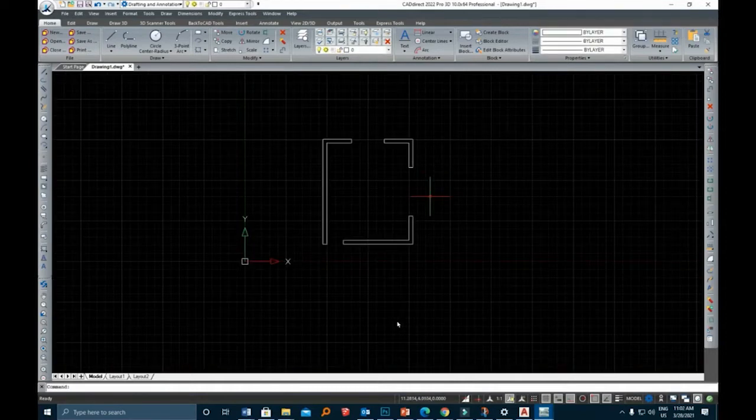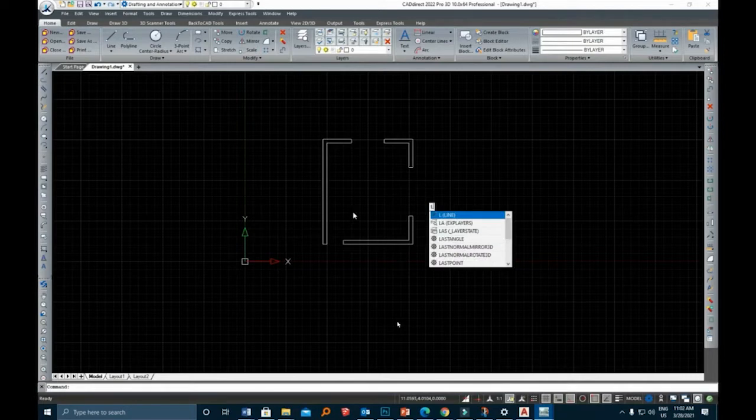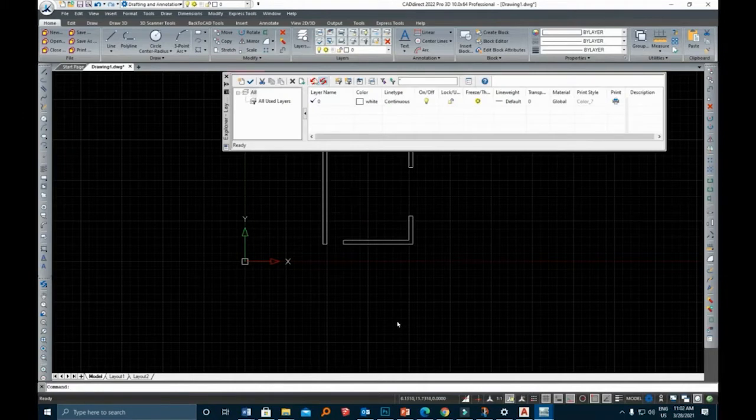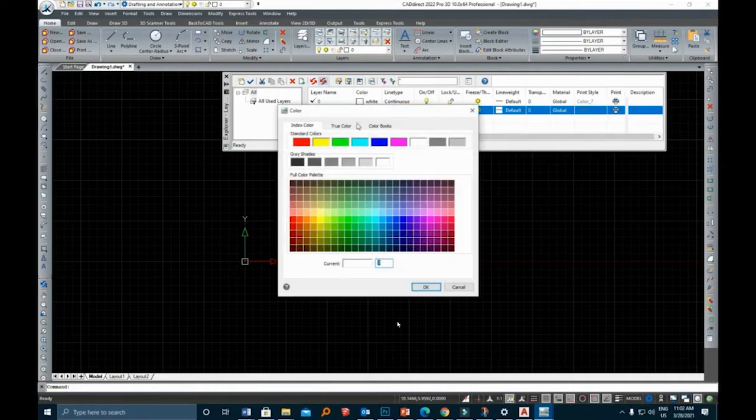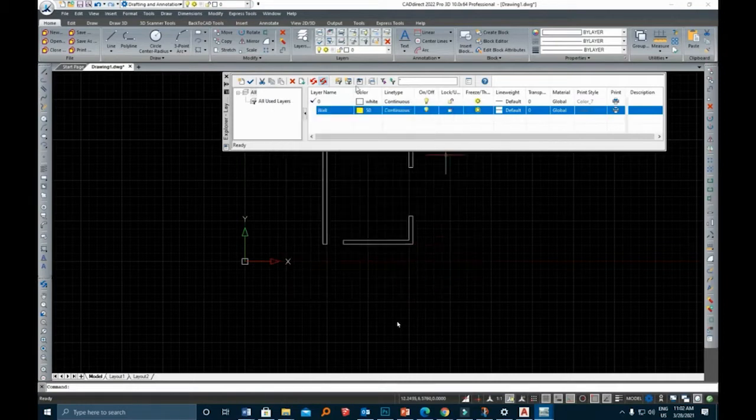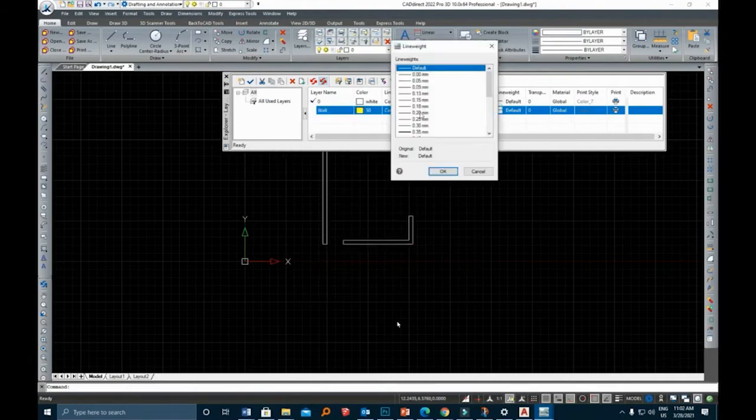So now I have given all the holes for doors and windows, and now I want to manage my drawing as different sets of layers. I want to put my walls in a layer, then windows and doors in another one. So this will make our drawing more conveyable. We can assign different line properties. We can assign different line characters and line type colors to differentiate between the priority of the drawing.